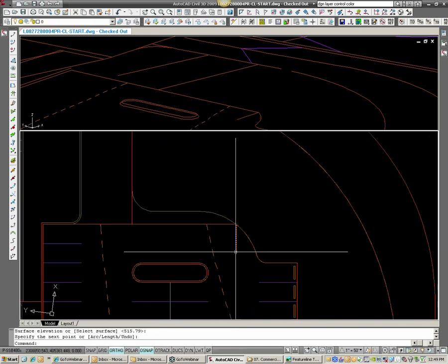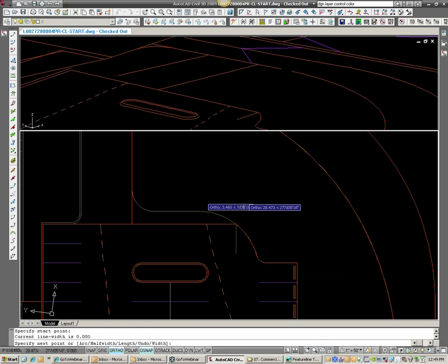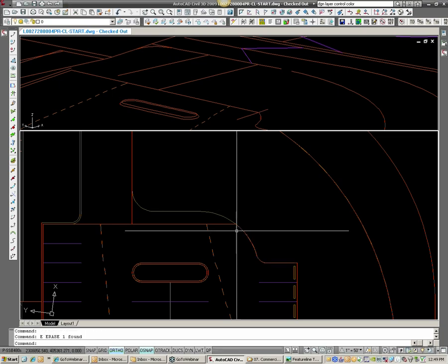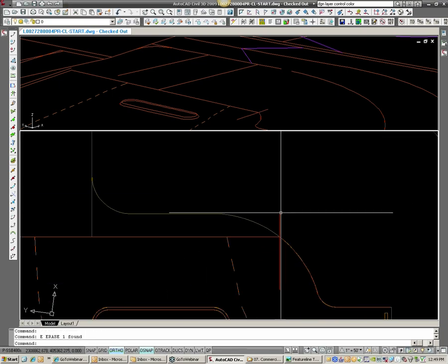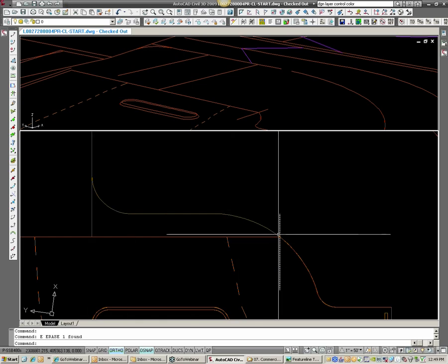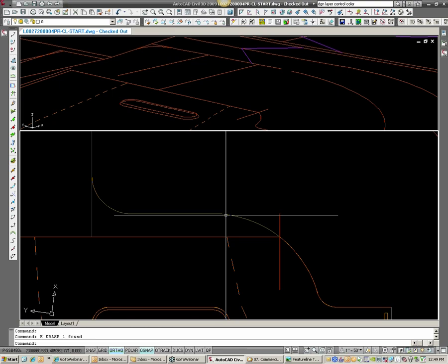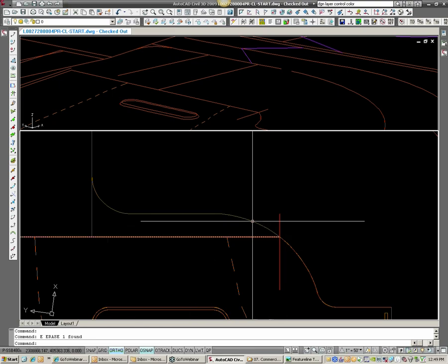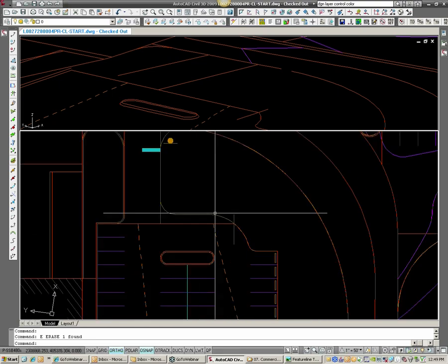So now I've drawn a feature line that inherited the cross slope of this temp grading surface. I'm just going to draw a construction line to extend that out to. I draw from here to here, and then I can just finish out that curve, draping it onto the surface to add this all to the surface and drape that on. And that's essentially how you need to really look at that. And that's what you do as you go throughout the entire site.